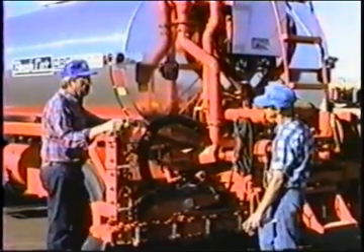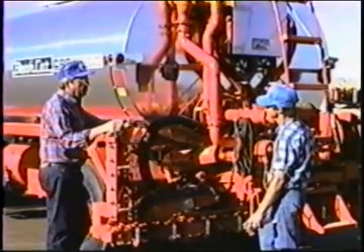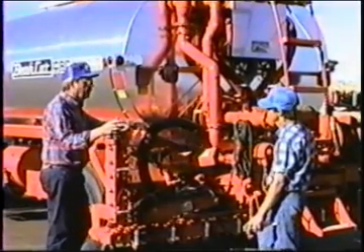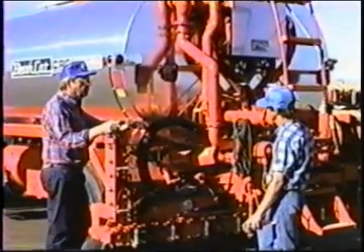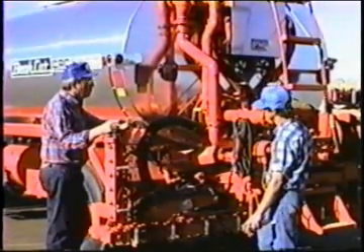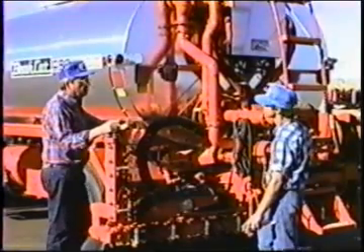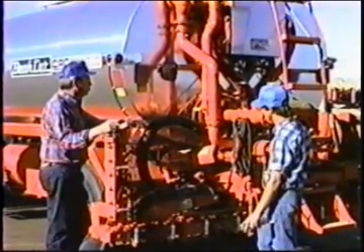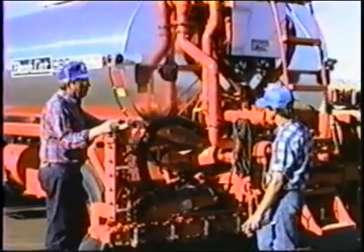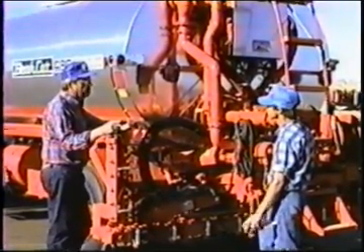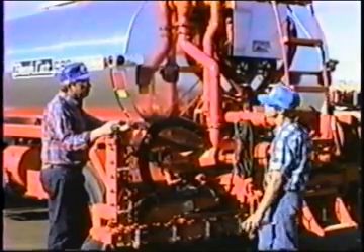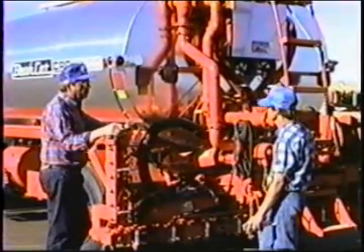If those gear teeth were filled up with iron graphite powder, then it would be a problem because that's magnetic. But normal rock, dirt, asphalt, none of that is magnetic, and what the sensor is seeing is the magnetic field going by there. Clean, this makes no difference at all. And the chances of it being filled up with iron powder are slim to none. So what we're getting down to is just the clearance. If that clearance is right, that's right. If the clearance is right and it's still not getting the right information, either it has a connection problem, the sensor is bad, or possibly there's something wrong with the computer itself.